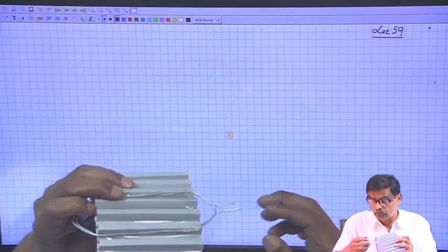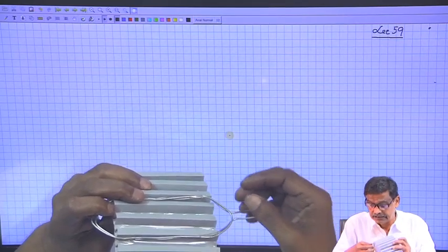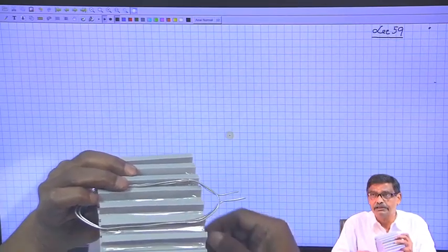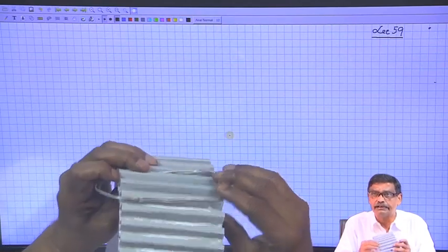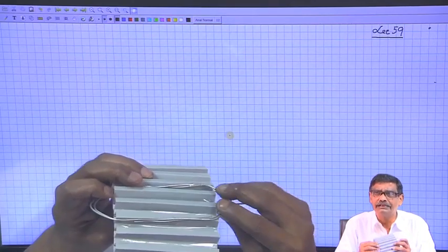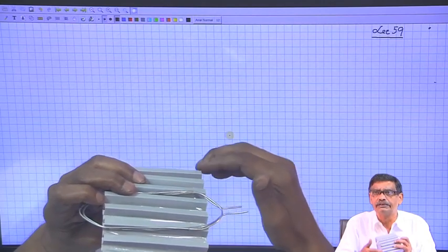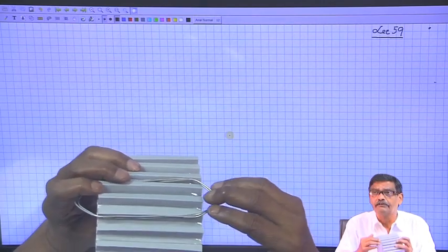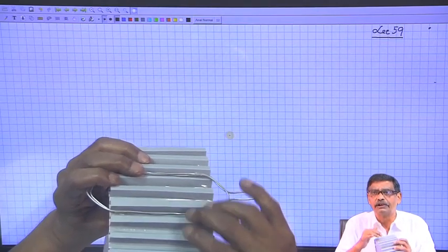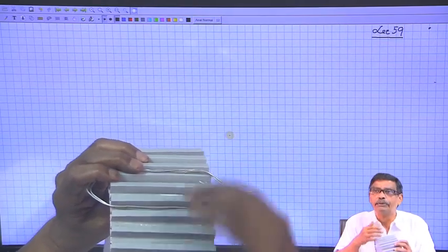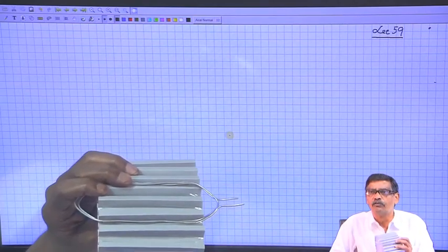So, I have to do something extra after getting this AC voltage in all the coils. Each coil is identical, same AC voltage will be induced. Only thing is the induced voltages will have some phase angle difference, because whatever is happening to this coil, after some time the same thing is going to happen to other coils. But nonetheless, the voltage will be of alternating type.